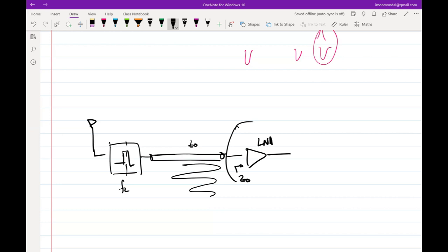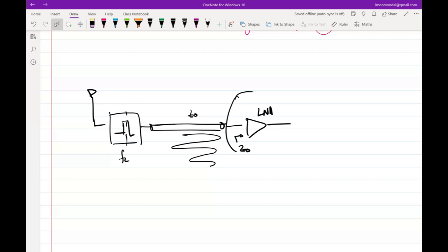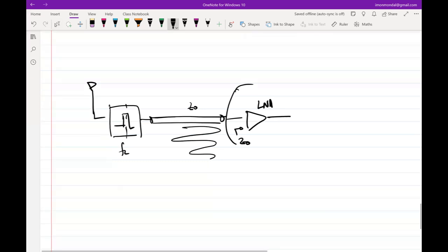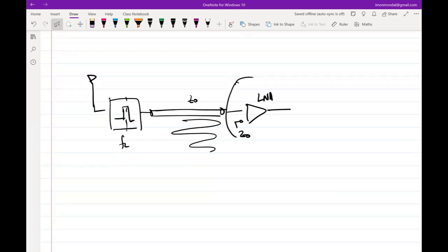Okay. So since you cannot control what the vendor is putting at the other end of the transmission line, you have to ensure that you do your job and make it matched, so that there is no further reflection at the LNA transmission line interface. Okay, fine. So now the question, basically then it boils down to what should be the characteristics of the LNA, right?